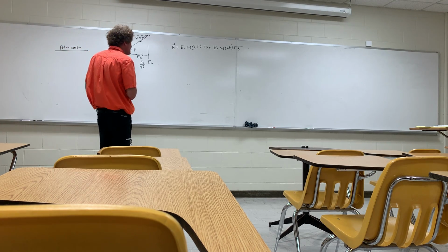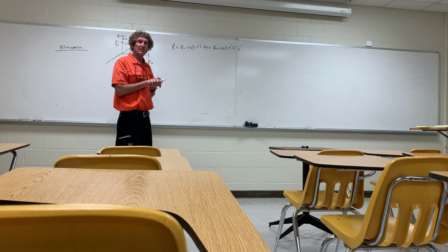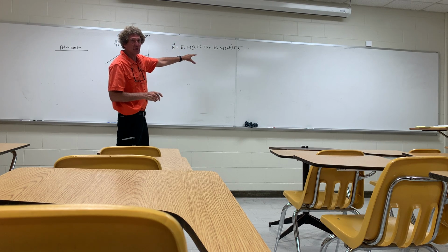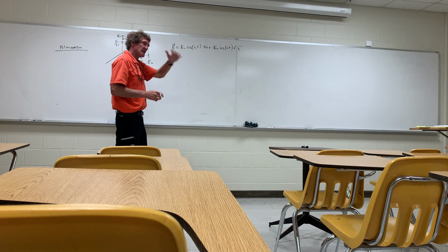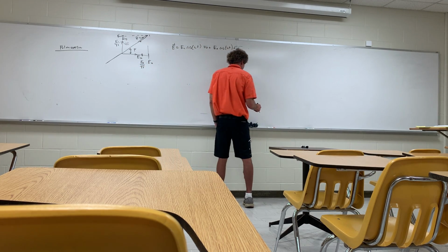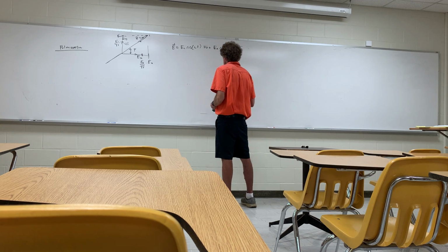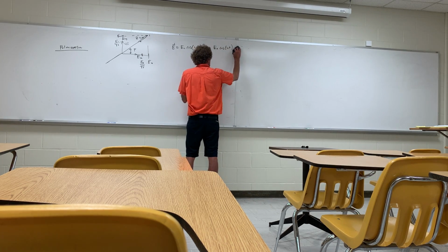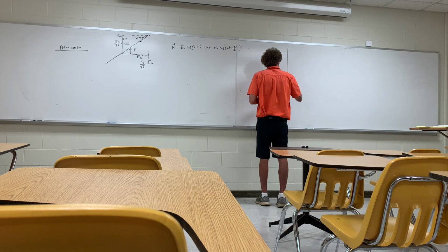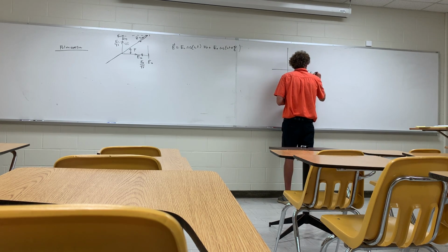Nobody cares about the tilt angle until you do weather radar and stuff like this, and then it becomes important, but not in a way that mathematically you have to do some clever thing. It's basically to get the maximum return at a certain tilt angle tells me the orientation of really the rain field. All right, so now the next case, I'm going to use this, but now I'm going to put a 90-degree shift here. It's going to be E naught cosine of omega t plus pi over 2. Y'all follow me? Same exact equation. This will be EX, and this is EY.